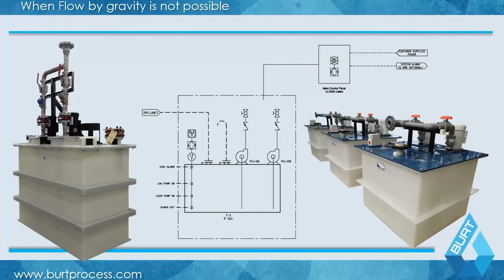A lift station is a little bit different than an EQ tank, because in an EQ tank you have a tank which you're holding waste for, basically buffering the volume coming into it. In a lift station tank, I'm basically just using this to compensate when gravity is not my friend. And like I said before, very often this is the case when you have subground drainage, or you're doing more of a renovation project and you need to tie this into a new pH neutralization system.